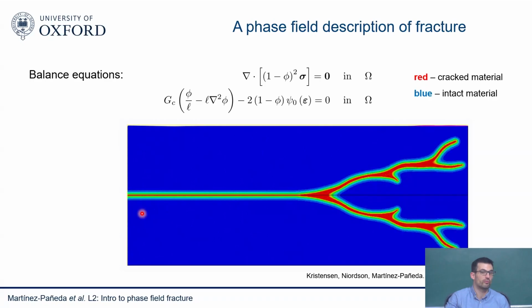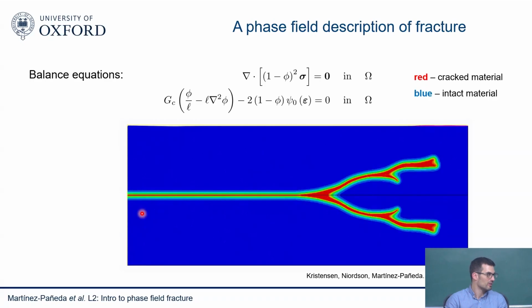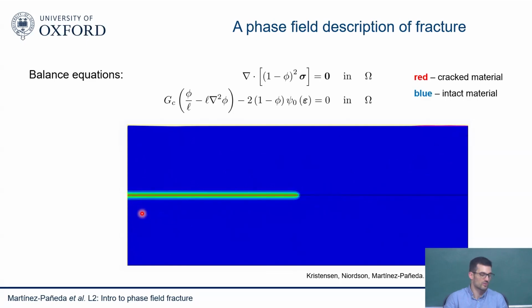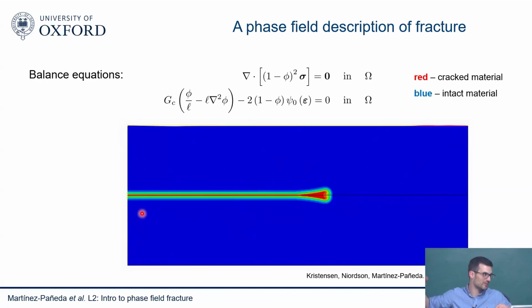And of any other fracture problem or damage model that relies on a fracture process zone, which are the only physically based ones, because you need to resolve the fracture process zone. So if you are trying to simulate something that is gigantic and you have a tiny fracture process zone and you don't know where your crack is going to go, and you want to model the propagation of the crack for the entire dam, then that's going to come at a cost.